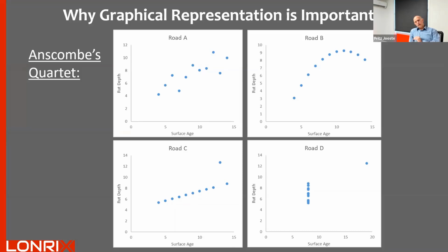So I really encourage you, when you are looking at your model outputs, when you're validating models, use JunoViewer's forecasting view to drill down on each treatment that your model is predicting. Go and look at the graphs. It's really easy. You select the treatment length or the modeling segment, and you can instantly go back into the historical data and see what the actual observed pattern of information is for that section of road.